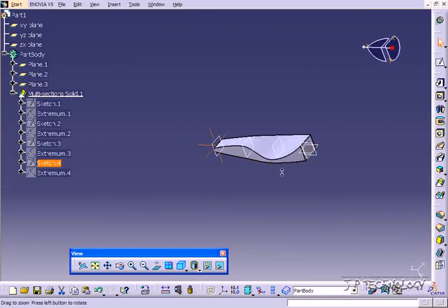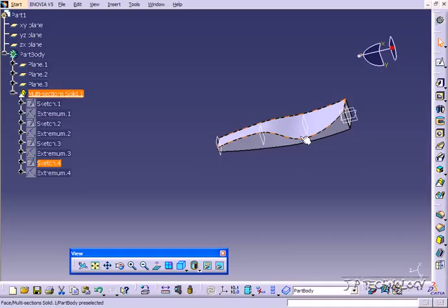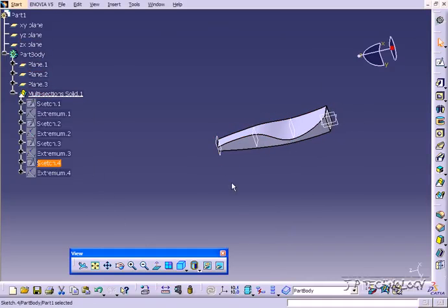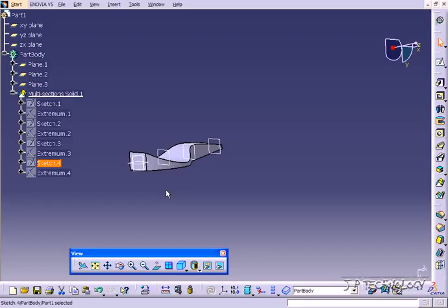And you can see our transition as we went from a square to a thin rectangle to a square back to the thin rectangle. So this is exactly the same as how we did the basic one, but this time we're using multiple sketches compared to 2. We're using 4 in this case, and you can use as many as you want.